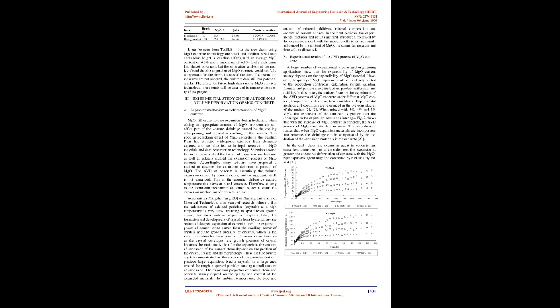The AVD observed by a stress-free meter embedded in Shuakao Dam is generally 40 to 60 times 10^-6, and conventional concrete measurements are 20 to 30 times 10^-6, and the effective expansion deformation is 60 to 80 times 10^-6, providing compensatory stress of 0.3 to 0.5 MPa. 26.